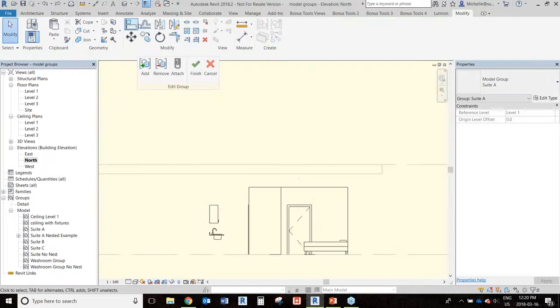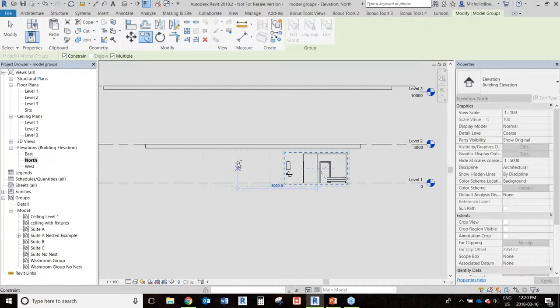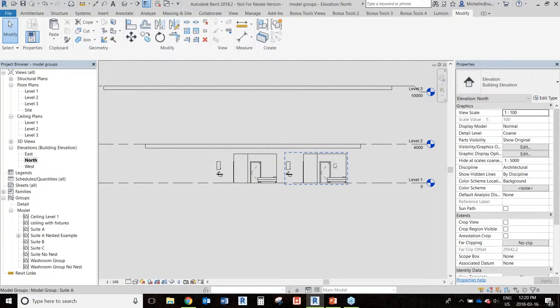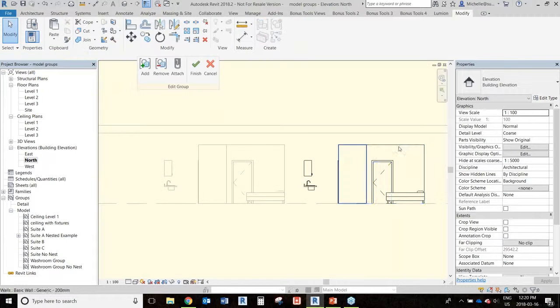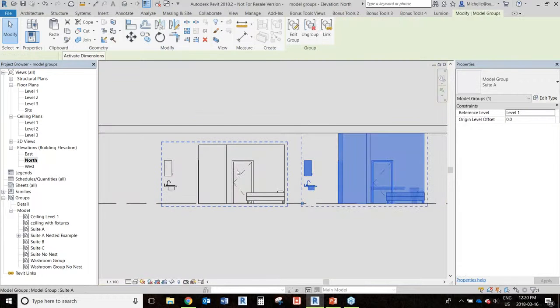Now, the other thing to note for this, the order is important here. So if I do that to one instance of my group, and I go in and attach this to the floor, it does not adjust the other ones. So this attach tool is kind of instance-based.